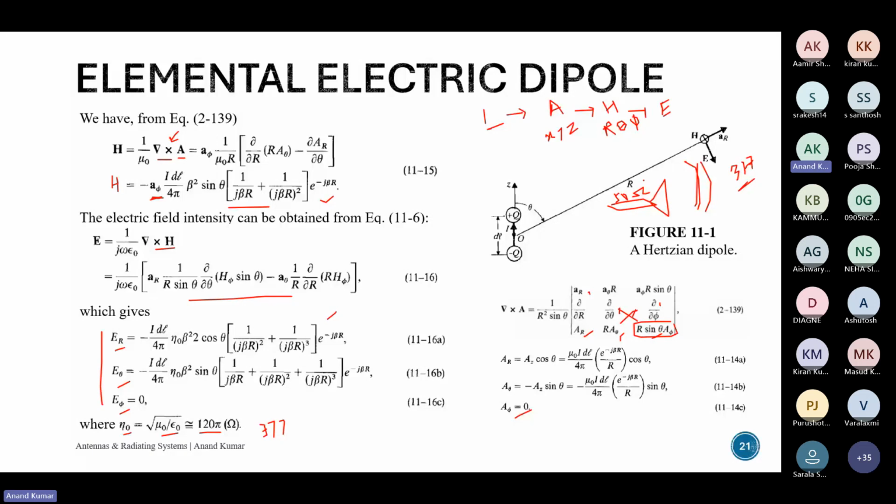If you match the impedance properly at that particular frequency, the antenna will radiate your wave which was on your circuit into the free space. Now again, the engineering problem becomes difficult if you want to launch a wider range of frequencies. Matching them at one frequency is fine, but if you want more frequency, so that's what an antenna problem is. You're matching your circuit to free space. Okay.